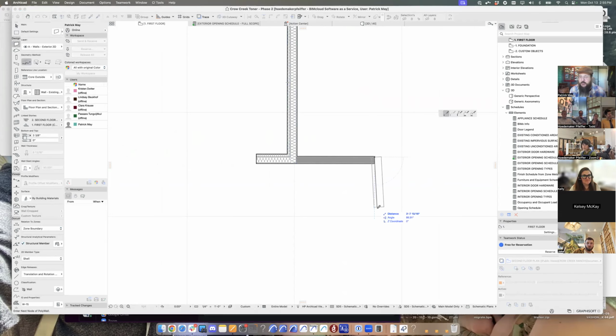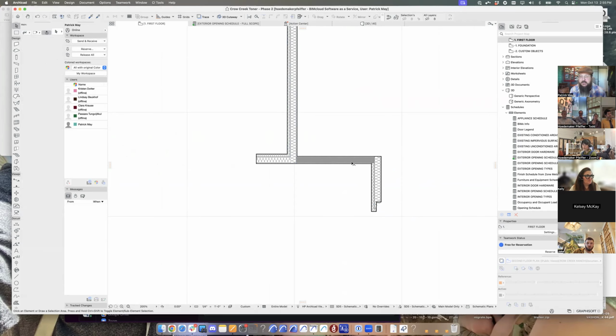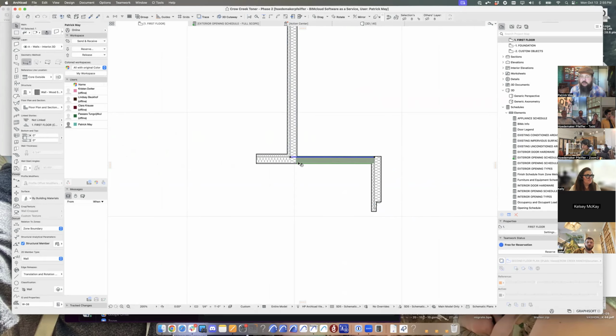Anyway, what's going on at the other end of this wall? And did dumbing down the junction order of this wall for this connection affect what's going on at the other side? So it can be a bit of a stacking the deck, or house of cards situation, where you get around the building and realize you've got a pinch point. There are extreme measures where you can take complex profile columns, not walls, and get things to come together at a single column. That's a very extreme case.